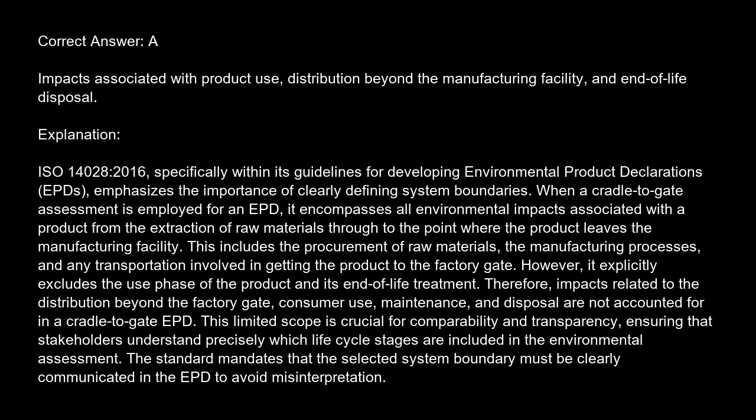Explanation: ISO 14025-2016, specifically within its guidelines for developing environmental product declarations (EPD), emphasizes the importance of clearly defining system boundaries. When a cradle-to-gate assessment is employed for an EPD, it encompasses all environmental impacts associated with a product from the extraction of raw materials through to the point where the product leaves the manufacturing facility.